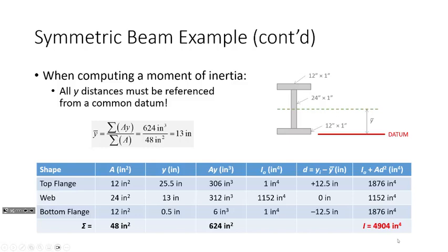Not the whole thing, just the center of the bottom flange. And to get from the very bottom of the cross section to the center of the bottom flange is an inch thick, so we're only talking about a ½ inch from the bottom. Everybody with me on that?